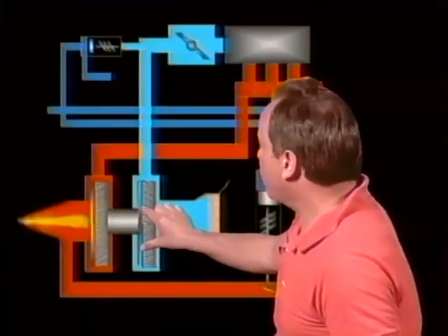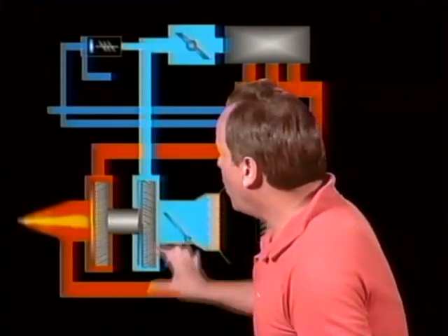So when you switch from low impeller to high impeller in a supercharger on the ground during a ground check, you'll have an increase in RPM and an increase in manifold pressure. And just to confuse you a little bit, to ask you about this, you'll also have a momentary drop in oil pressure because oil pressure is used to switch from low impeller to high impeller. That's it. That's the big question they ask you on the test about superchargers right there.